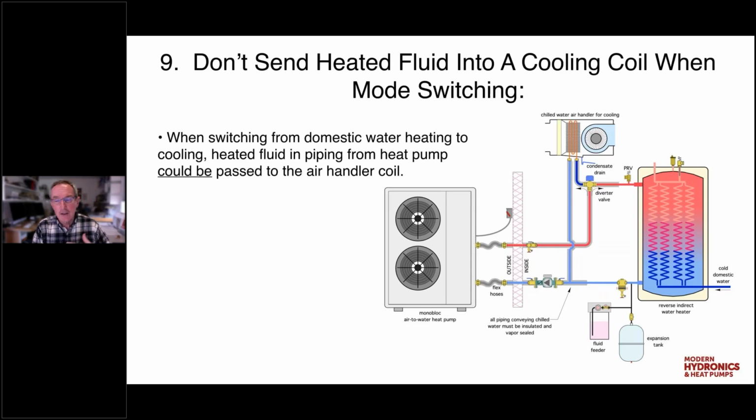And if we immediately direct that flow back up to the coil in the air handler, we're going to get quite a burst of warm air, at least for maybe a minute, minute and a half, while that circuit cools down. And it's almost guaranteed you're going to get a callback on that. Somebody thinks we're turning on the air conditioning. Why should we experience this blast of warm air, even though it might only last a minute?